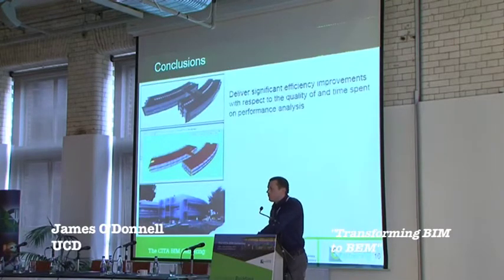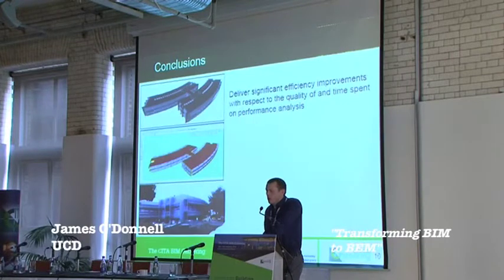Okay, so to conclude, this process delivers significant efficiency improvements, and to date, a lot of the energy modeling activity, because it took so long, and Bazjanac in one of his earlier papers claimed that 90% of the modeling effort was associated with the building geometry, and for that reason you could only develop one real model in detail, and if the design evolved past that point, then your model was out of sync with your design state. So I think this process enables a synchronization of the design with the energy model predictions for that particular design.